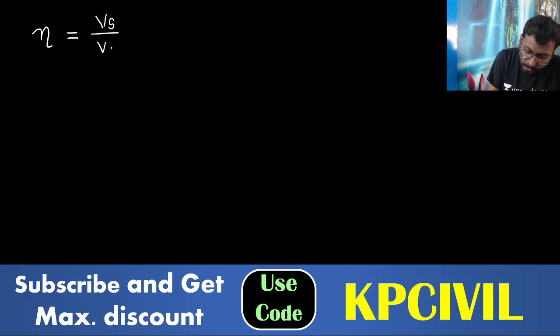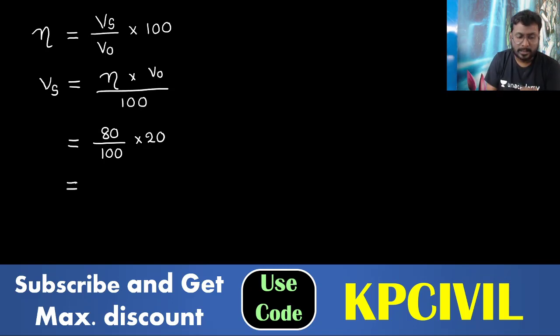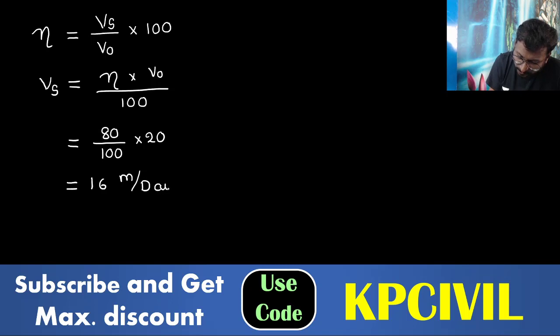So we have the formula related to efficiency. Efficiency is equal to Vs upon V naught into 100. What is Vs? We have to determine now. Vs is equal to efficiency into V naught by 100. Efficiency 80%, so 80 by 100 into V naught, which we have already taken as 20. So what is the value? 16 meter per day. Vs is 16 meter per day.